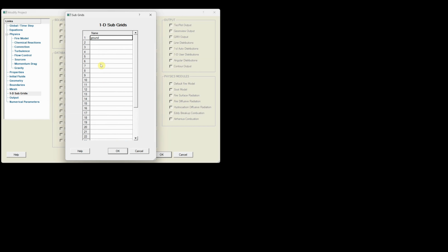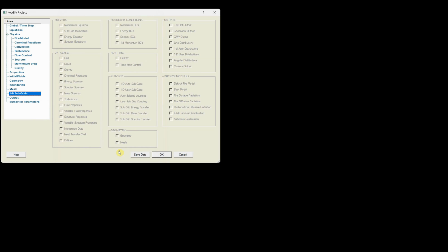We have to click on some boundary conditions, and it'll be adiabatic no flow. Those are the defaults, and we'll just take the defaults. We've got air, concrete, and we're going to do auto coupling. And we're going to couple it to insulator 1. That was what we built the ground out of. And we're going to search the entire domain for that material. So that should cover that. I don't think we're going to couple to the stack. We'll leave that alone. So we're just going to get ground fluxes.